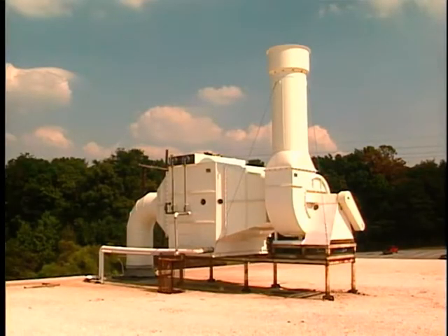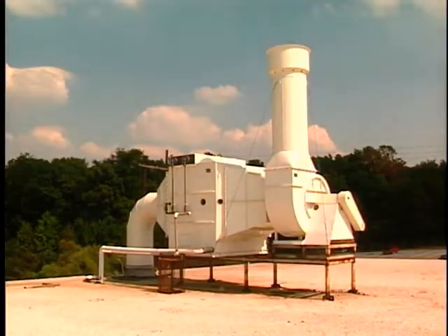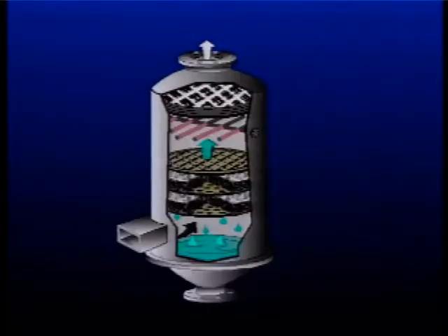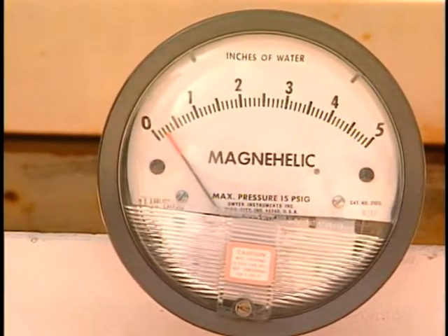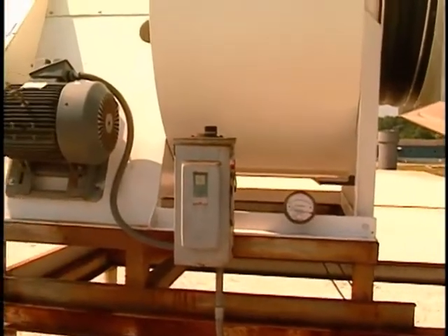Increased pressure drop across the absorber may indicate plugging of trays or packed beds. A decrease in the pressure drop across a tray absorber may indicate warped or collapsed trays. Similarly, the pressure drop across the mist eliminator provides an excellent indicator of its physical condition.